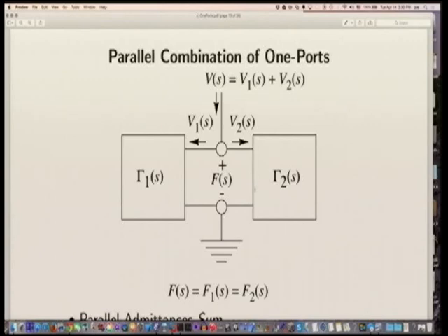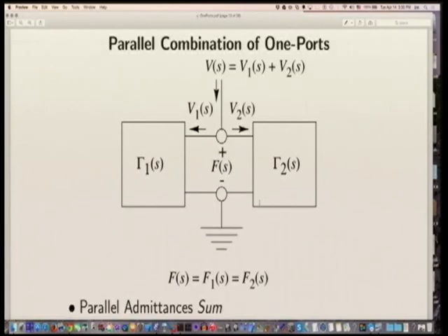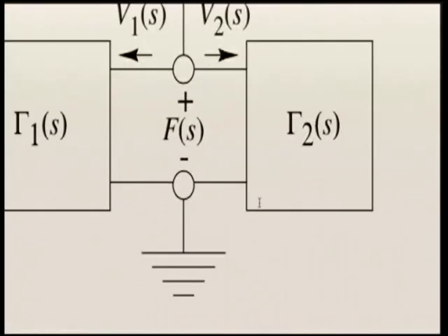That's an example of what you don't do. I mean, you'll still do that, but in that case we'll have just a transfer function from one to the other. But it won't have magic properties like being positive real. And that's where I'm going with this. It turns out that every passive one port is positive real. And of course, I'm assuming linear time invariant.